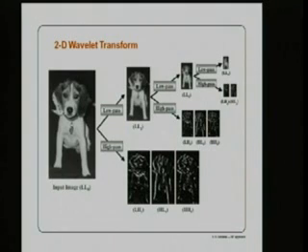Now, the high-pass filters are going to be high-pass directionally. So if I low-pass filter in the horizontal direction and downsample, I just have a blurry, skinny version of the image. But then when I take that and high-pass filter it vertically, I end up passing the horizontal edges. And that's what we see in the first output. We get very strong horizontal edges and not much else. Change the direction that the filters are operating, so now I'm high-pass filtering horizontally, we see the vertical edges. Okay. And lastly, we're going to high-pass filter in both directions.